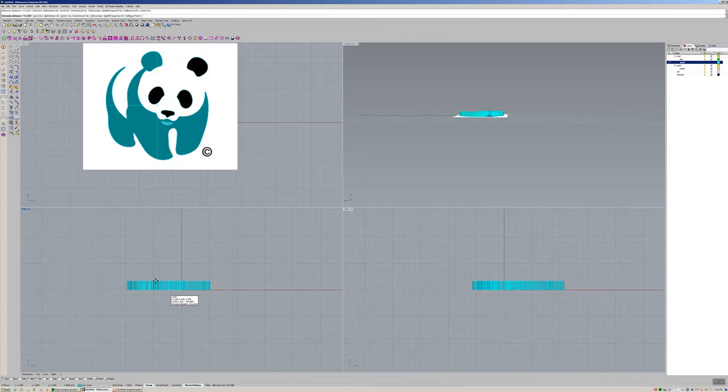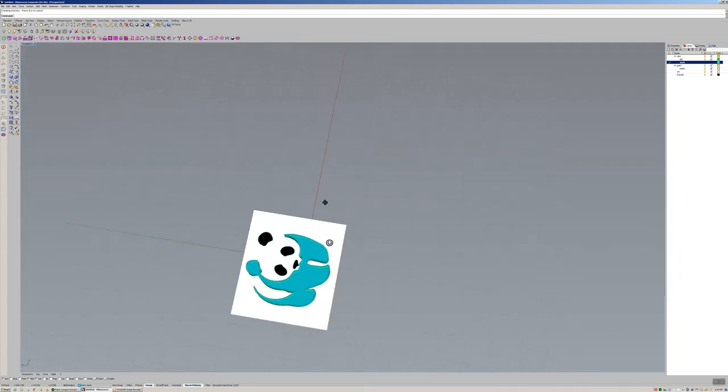Another thing to remember is we can punch in the number of units. So each box is a number. I have it set to millimeters. So each square is 1 millimeter, 1 millimeter, 2 millimeter. So if I hit 2 enter, it's going to do 2 millimeters. So that'd be 2 millimeters thick. Yeah, 2 millimeters thick. Now, if I go to perspective and take a look, you see the chin